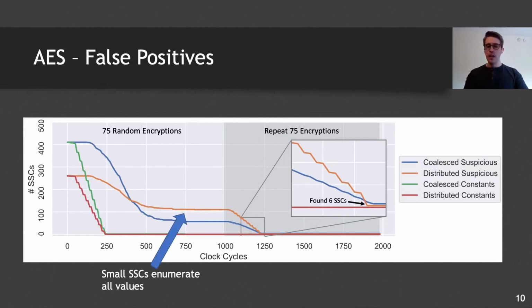At this point, we recognize that it is infeasible for Bomberman to observe the same for large SSCs in any reasonable amount of time. To overcome this, we make another observation: since the AES core is a deterministic state machine with no control path SSCs, repeating input test vectors will cause all deterministic data path only SSCs to repeat values, violating the other TTT invariant of no repeated values.